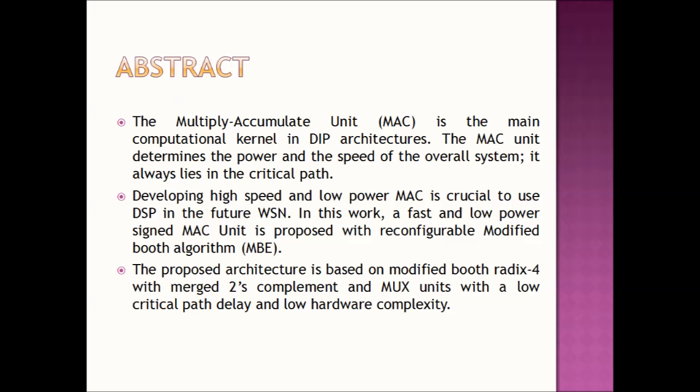In this work, a fast and low power signed MAC unit is proposed with a reconfigurable modified Booth algorithm. The proposed architecture is based on modified Booth Radix-8 architecture with merged 2's complement and MUX units, with a low critical path delay and low hardware complexity.